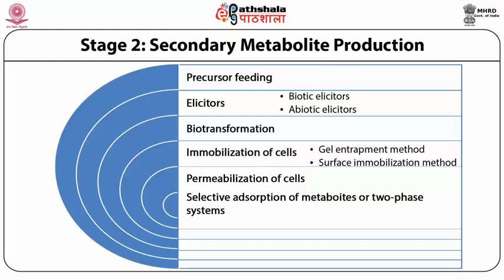Some of the materials used for the removal and sequestering of the product are polycarboxylic ester resins and neutral polymeric resins, and these can adsorb these secondary metabolites. And in a few cases, activated charcoal, RP8, which is a lipophilic carrier, zeolites, polyethylene glycol, and cyclodextrins are all used to help in separation of the secondary metabolites which are produced, so that the process is more efficient.